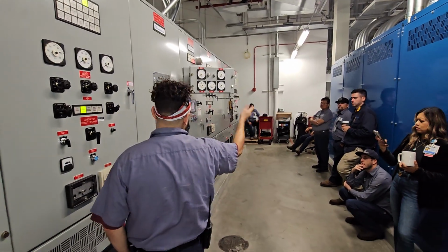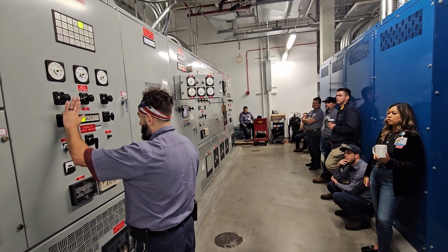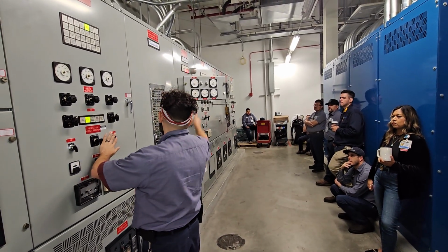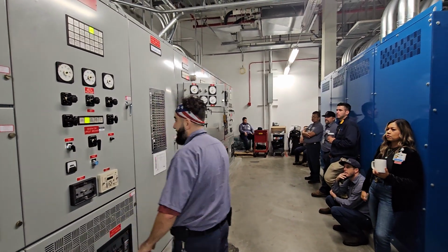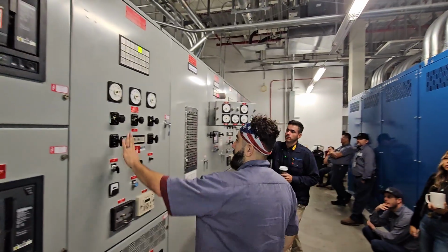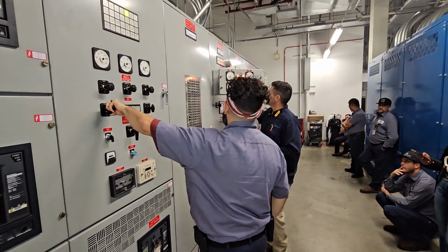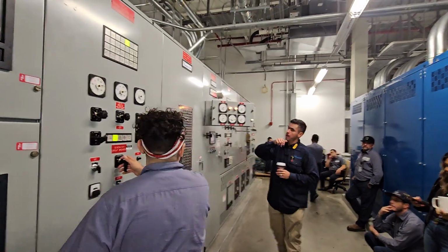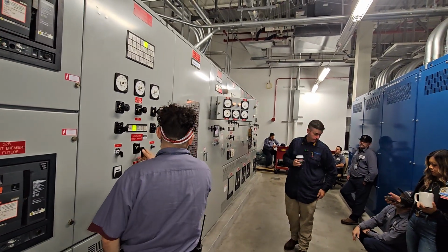But you already checked it. We got the 60 hertz on both. This is my key, but I don't want to close it yet because I gotta do the thing where it's in the center. So that key enables your breaker control, but also turns on the synchroscope. In order to watch this, and then I close it right quick. Not until you're at 12.